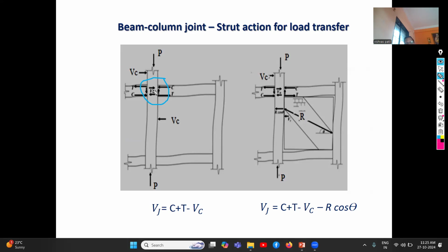Shear hinge is also available in SAP 2000. The user only needs to calculate the shear resisting capacity using the appropriate code, and just give one input for that. I will show that also in SAP 2000, where this input is to be given.